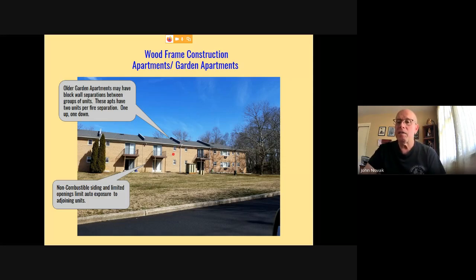The siding, a brick veneer siding, so not combustible. Fire gets on the outside of the building. It's not going to be a fuel package to extend fire up from the siding material into the exposure, into the soffit. Even fire venting out the slider here is more than likely not going to get up into the soffit around that firewall in these type of buildings.